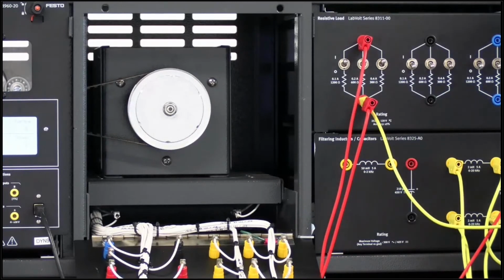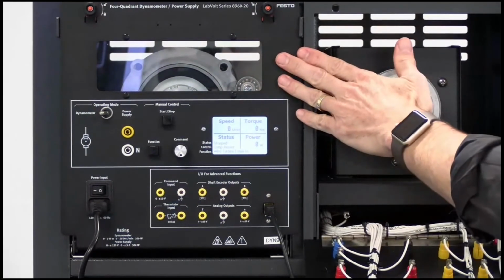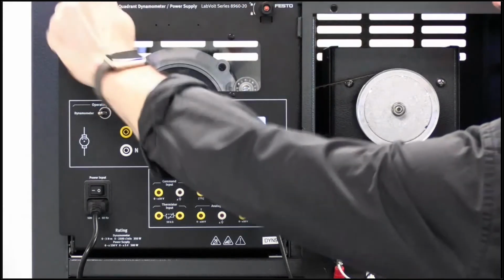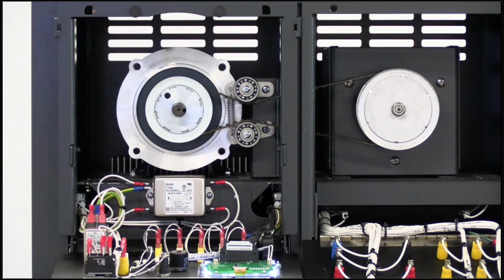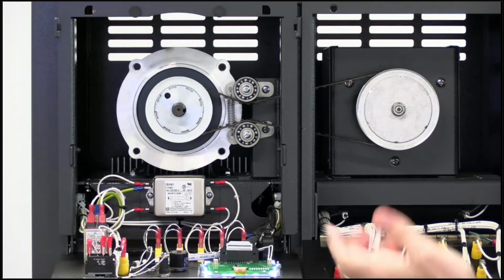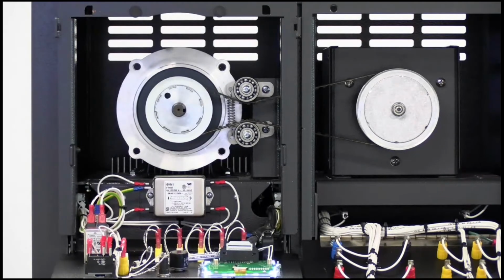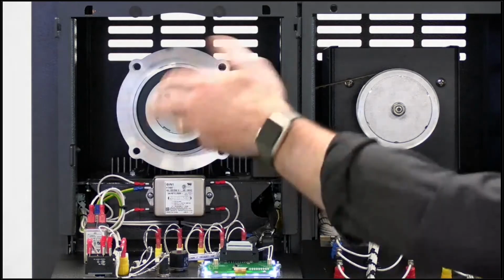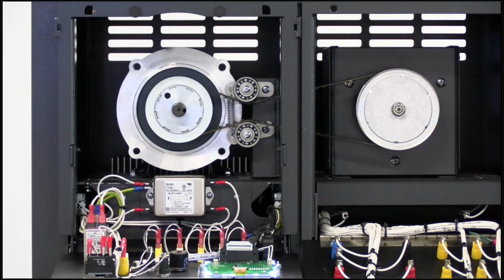So to this purpose, we will use the dynamometer that is right to the left of this unit here. So this is our 4-quadrant dynamometer unit, that is simply a DC motor that is computer controlled, and that we will be able to ask to behave as if it was a wind turbine or wind rotor connected to the generator. So we will see in a moment that with the software that controls this motor, we will be able to say, okay, emulate a turbine of this type with a wind of this speed blowing on it with an air density of that value, and it will, depending on the values we set to these parameters, behave accordingly and drive the generator here as if it was connected to an actual wind turbine.